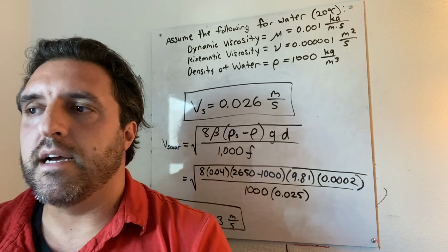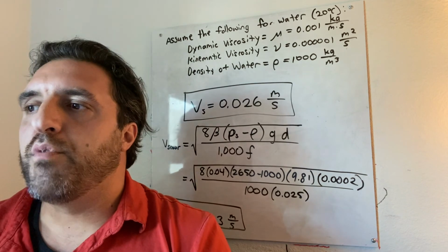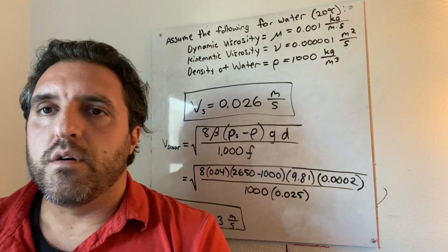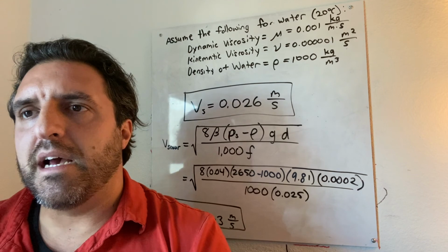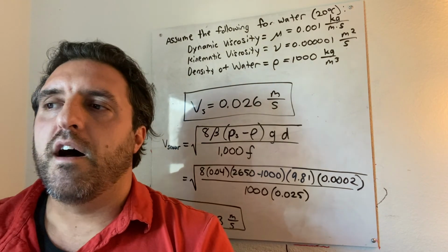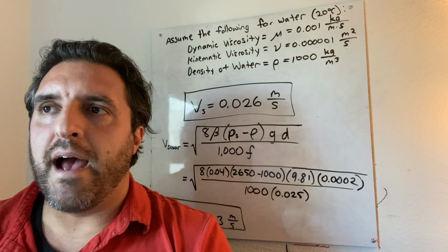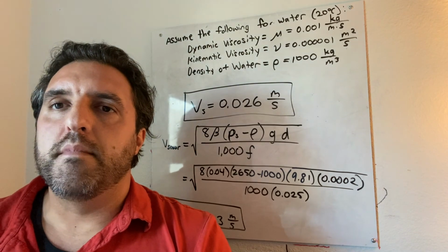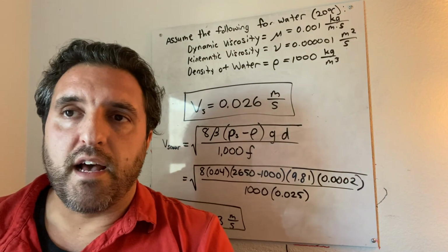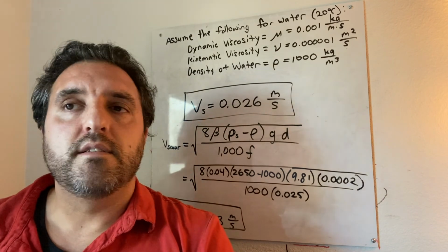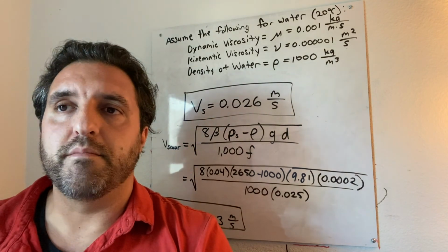They're more along the lines of 1.52. So given that information, we can expect that the settling velocity of most grit particles would actually be slower than the settling velocity for the more dense sand particle of 200 microns.